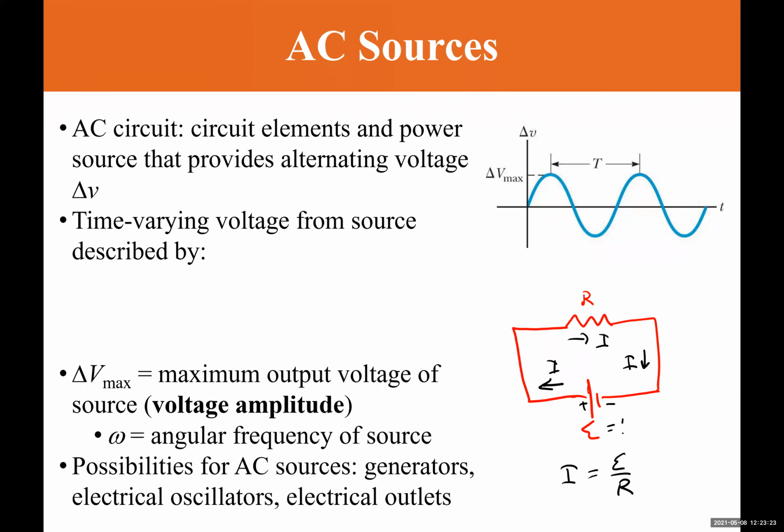So let's say this is 1.5 volts, then it's a 1.5 volt EMF. Resistance is always a constant quantity. For example, let's say it's 10 ohms. So then what you get here is 1.5 volts divided by 10 ohms, which gives us 0.15 amps or 150 milliamps. That means the current is going to be 150 milliamps, or 0.15 amps, basically the entire time you're operating the circuit.